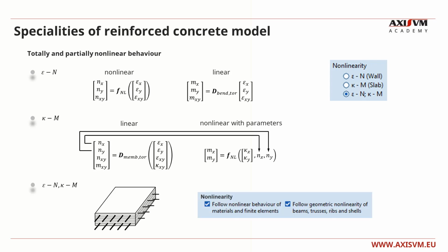For three-dimensional shell models, the totally nonlinear model is suggested. It is calculated on the basis of a materially nonlinear fiber model with coupled membrane forces and plate moments. For the occurrence of normal force due to deflection, the geometric nonlinearity is also necessary to be turned on.